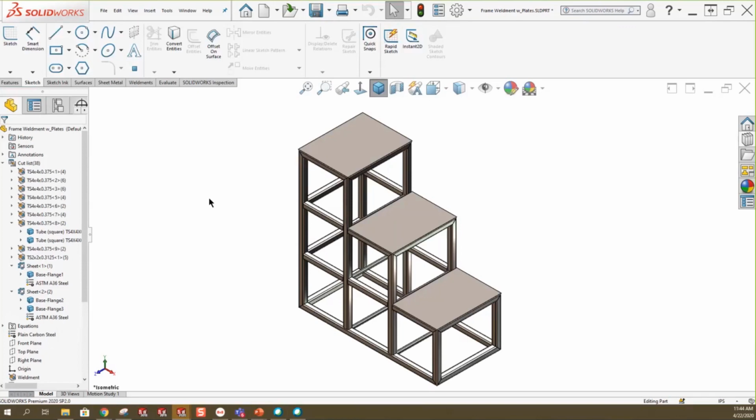You forget to save the assembly off, everything that's related to Assemb1 or whatever assembly you're on. Then when you try to rename your assembly, it goes, well, no, I've got all these parts that are associated to Assemb1. By the way, you ever run into that, your solution to that is pack and go. Do a file, pack and go, rename the files, maybe put them somewhere else, but rename that assembly file, and all of those in-context relations will update to that new file. The only way out of that one.